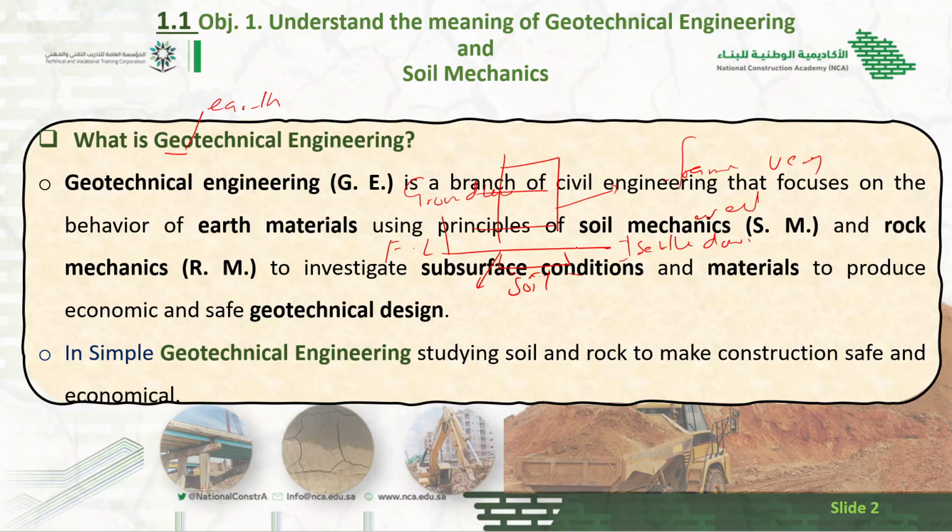It means, as you know, all civil engineering structures, either a building, or transportation, or any marine structures, they all are built or constructed on the ground. So all the loads at the end transfer to the soil. If the soil is strong, having good bearing capacity, then our structure will sustain. Otherwise, if we design our structure very well but the soil bearing capacity is not good, at the end, after some time, our building becomes what?